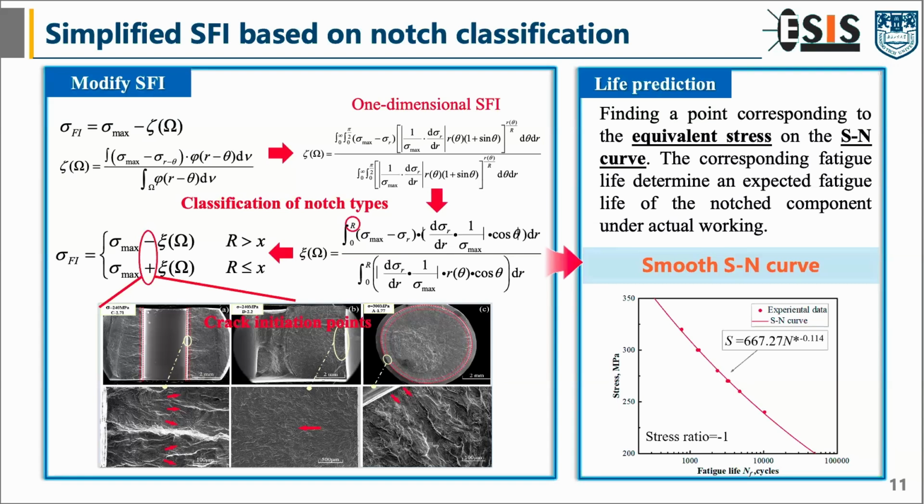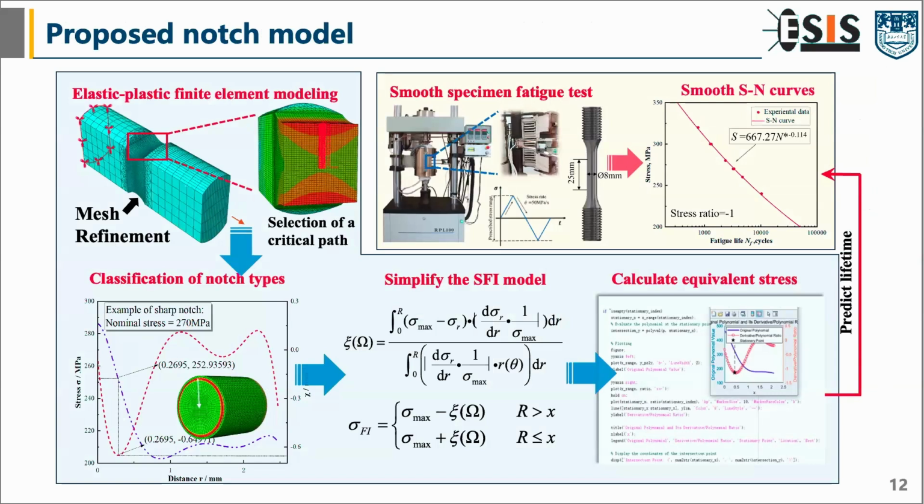Specifically, we find a point corresponding to the equivalent stress on the SN curve. The corresponding fatigue life determines an expected fatigue life of the notch component under actual working conditions. That's all about the proposed notch model, and let's make a summary.